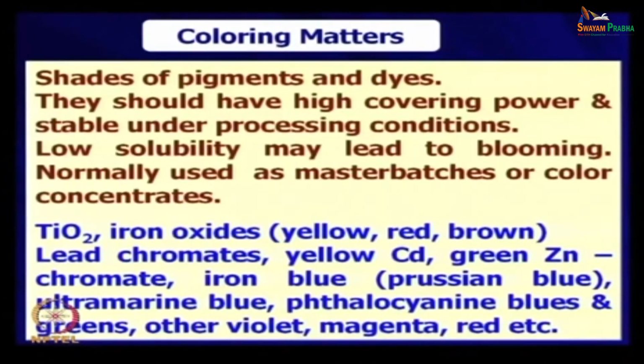Now, you see, for white color what we use? Titanium dioxide, zinc oxide, good whitener, good white shade. Over that you can put a tinge of some other color, that may be again some inorganic materials, say iron, cadmium, copper, barium, chromium. Compounds or oxides of these elements are good pigments, and these pigments are used in fine particle powder with the polymer for coloring purpose.